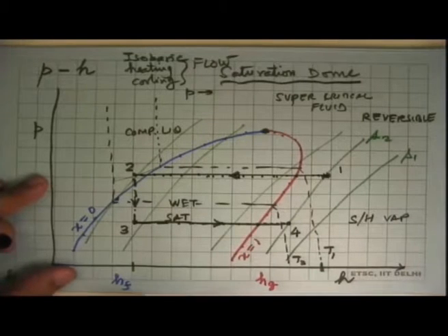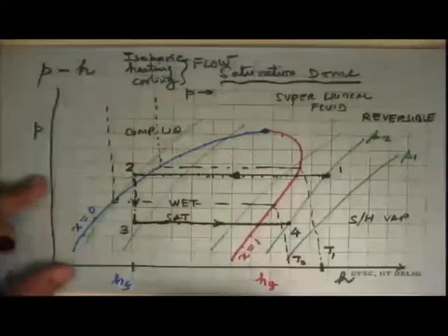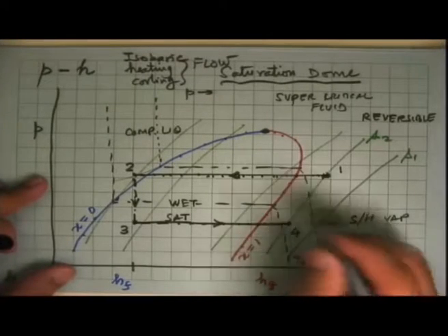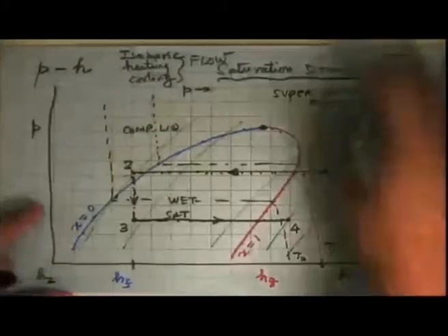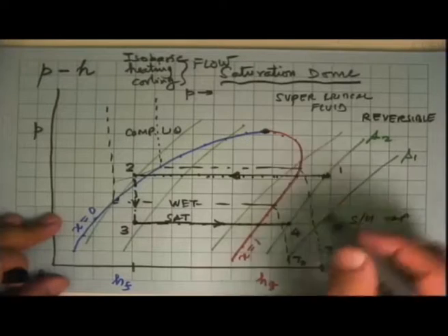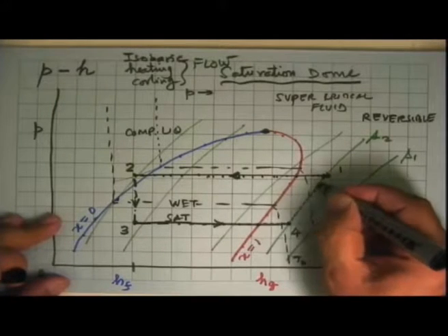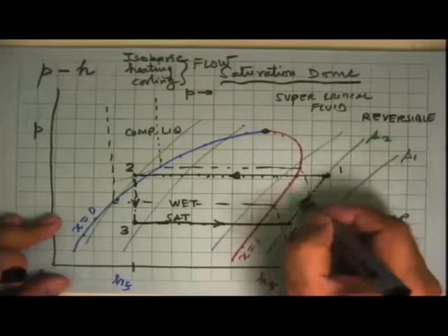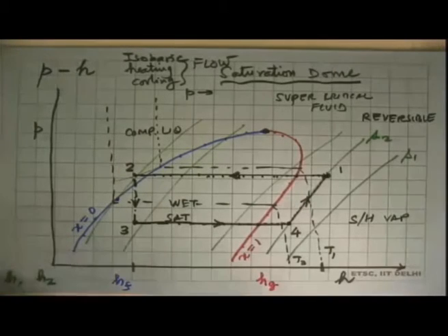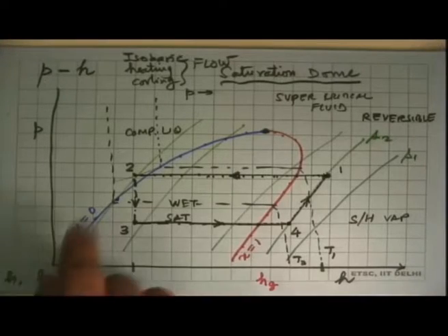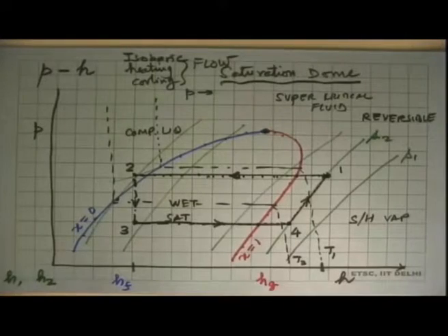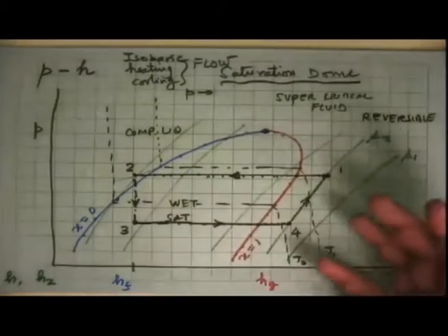That's what was happening. And to complete this refrigeration cycle, we say at this point it enters the compressor, and if we assume that the compression process is reversible adiabatic, it means that it is an isentropic process, then the process inside the compressor will go along a constant entropy line. This will again have to be a solid line, and that is our compression process. And so very nicely we are able to visualize what this diagram looks like. And also we can even get quantifiable data.